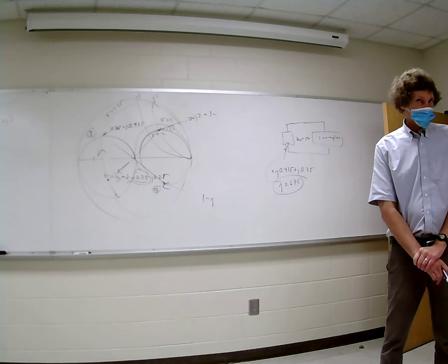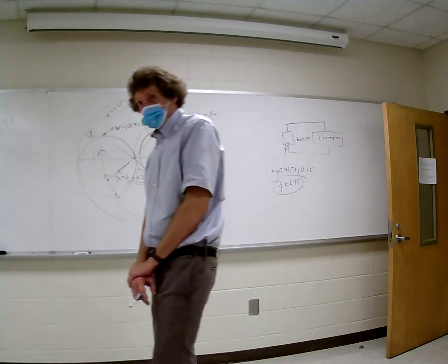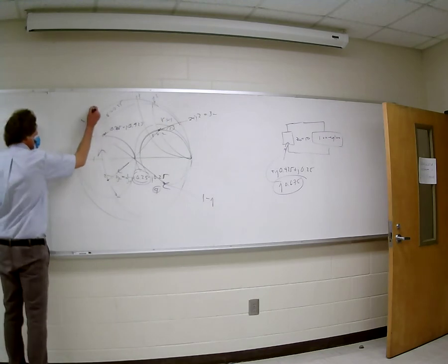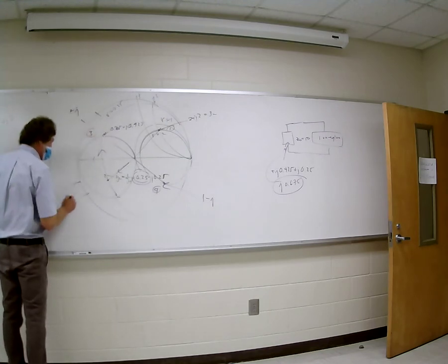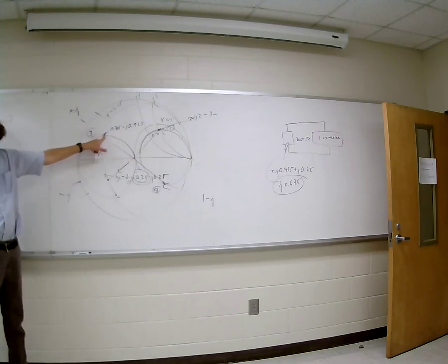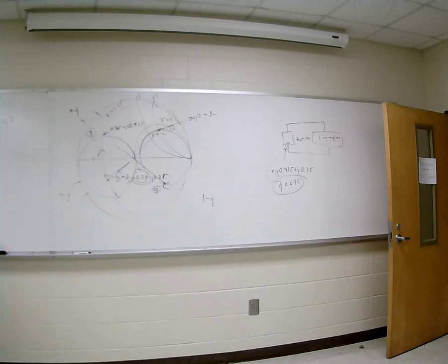So whenever we go to the admittance domain, we can't use this Smith chart. We have to use the rotated one. You got a rotated circle. Yeah, I drew it. Those values are the mile markers. Those are the plus j values. These values are the minus j. This is a road map. The only thing you're doing is finding the geolocation of that point: 0.25 plus j 0.425. Anywhere on this circle, we can find a point that defines it, right? Doesn't matter where you are.